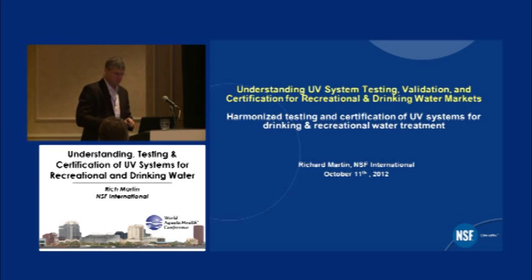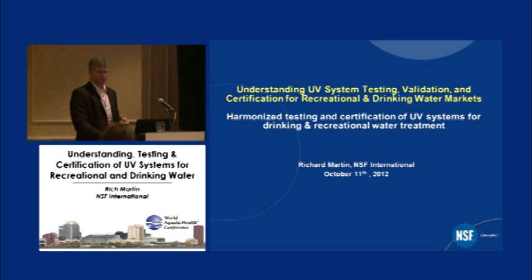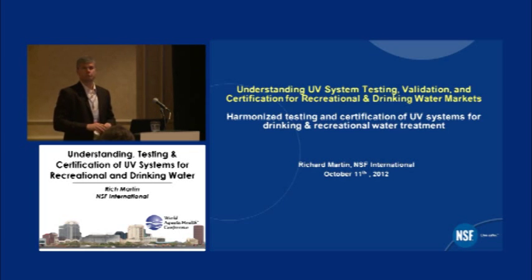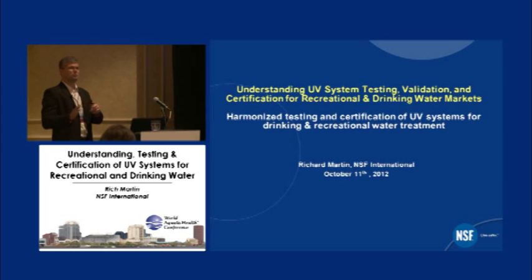sort of grim material. Anyway, what we're going to be doing today is just an overview of some of the interaction between standards, the code development process, and how that specifically applies in the evaluation of UV systems. UV systems, as you're all familiar with, are obviously used for what some people call supplemental treatment, but I actually consider it primary treatment for certain types of organisms, such as Cryptosporidium.